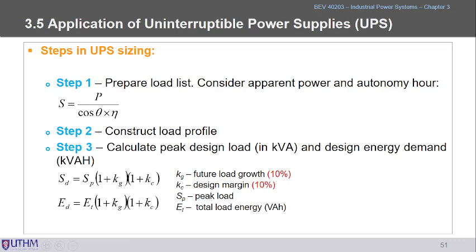Step 2 is to construct the load profiling. So we need to draw the load profile in this case. We'll have one example later on to see this one. And step 3 is to calculate the peak design load. We need to calculate what is the peak design load, in kVA, so that we won't lose the power. We always seek the peak design load so that we won't get any power outage or not enough power later on, and the design energy demand as well, in kVAh.